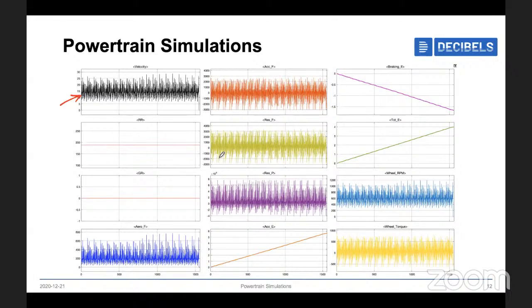So it's maintaining the constant throughout the drive cycle. We can also make it dependent on the drive cycle, which means a function of velocity. When the velocity crosses, let's say, 30 kmph or something like that, we can make it dependent on velocity. It's up to you what accuracy level you want to develop the models to. And next one is grade resistance.